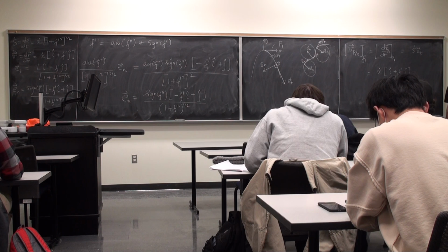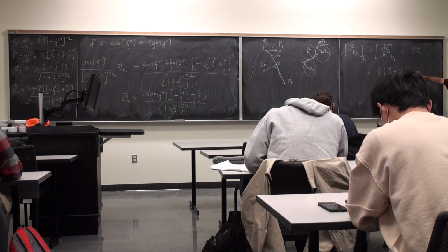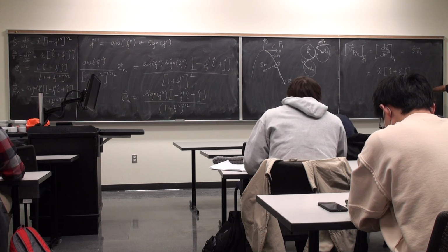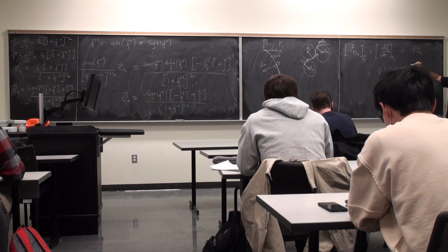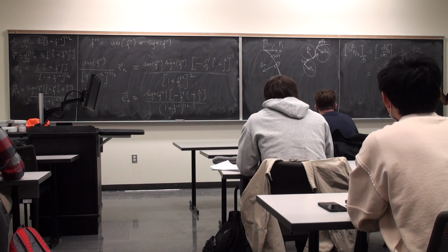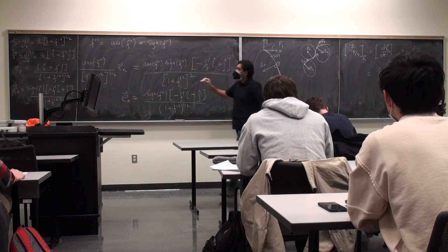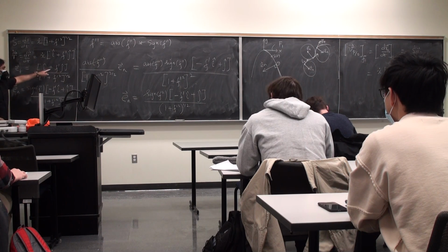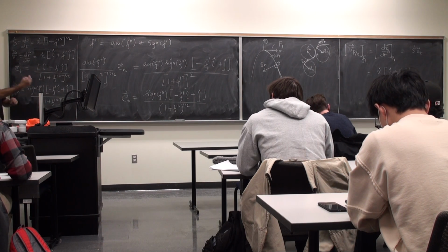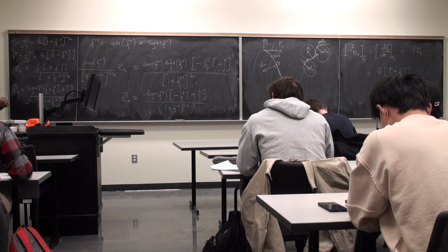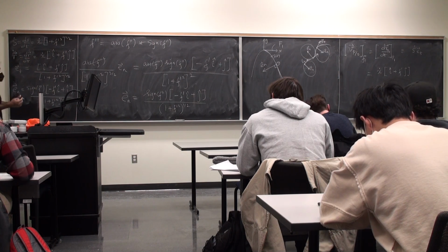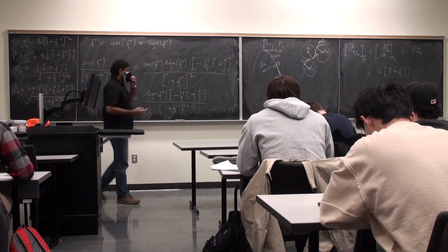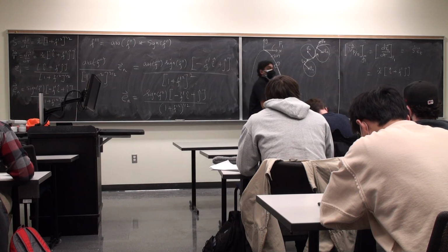And you can do the following. You can substitute for i hat and j hat in terms of the tangential and the normal unit vectors, by using the transformation equations here. If I write et as a function of i and j and en as a function of i and j, I can do the inverse transformation as well. Okay? And you can do the substitution, and you'll end up seeing that the normal components will not play a role in the velocity. You'll end up getting s dot et.